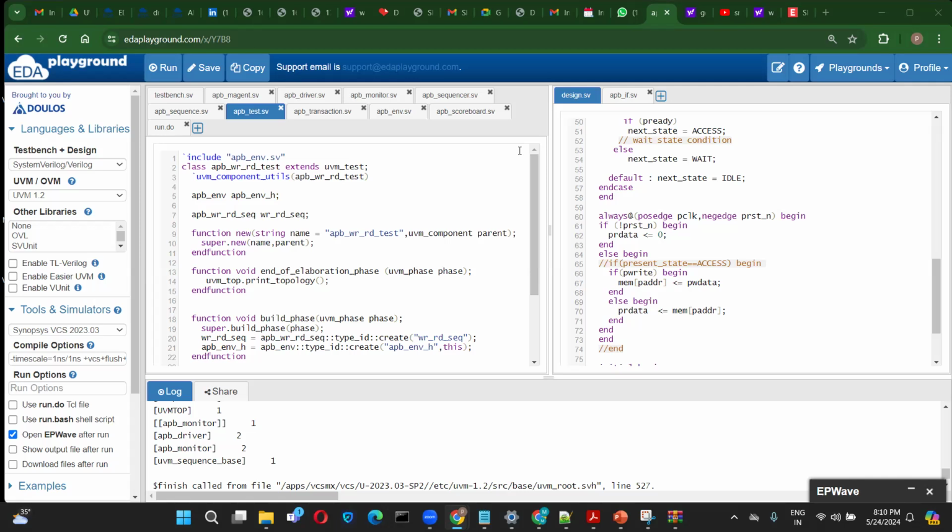For example, in I2C, we have different bus speeds. Then there are different things, right? For example, in the APB, we have write, read. For that also, you can create an enum. We can include all those enums in one particular file. So it all depends on how we do it. Here we are doing it this way. There is no rule that we have to do it the same way. There are so many other ways, like you can create packages also.